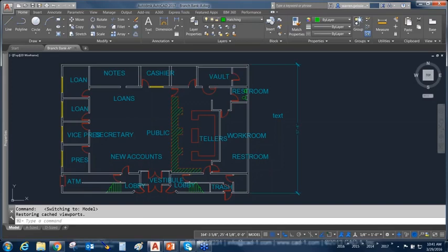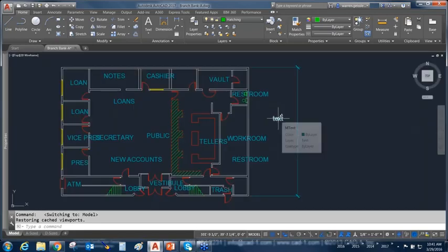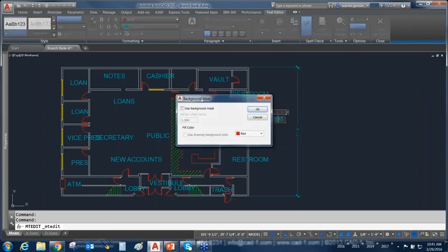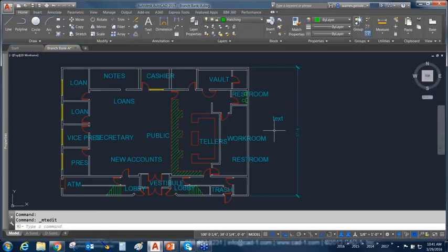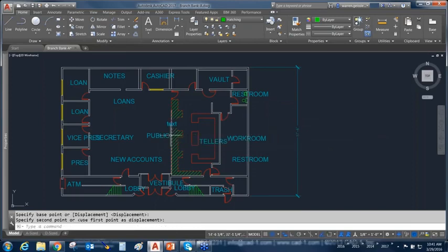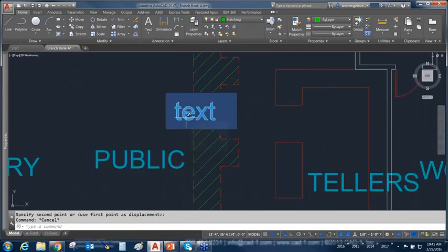And I see one other question from Dwayne, annotative scaling and masking. And I'm assuming, Dwayne, you're asking about the text mask for annotative scalings. The text mask works the same way. Let me stretch this little guy in here. So text masking works the same way that it pretty much does anywhere. I can use a background mask and my drawing scale color. And what masking does is, when I grab this and move it over top of something else, you'll notice that it masks it. And that's the size of the text box.